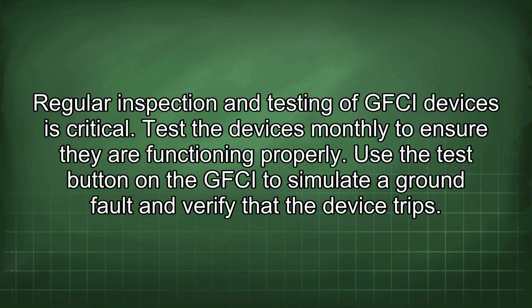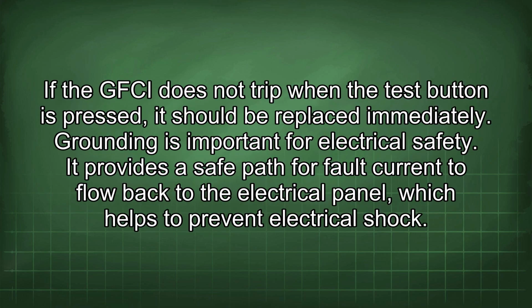Regular inspection and testing of GFCI devices is critical. Test the devices monthly to ensure they are functioning properly. Use the test button on the GFCI to simulate a ground fault and verify that the device trips. If the GFCI does not trip when the test button is pressed, it should be replaced immediately.